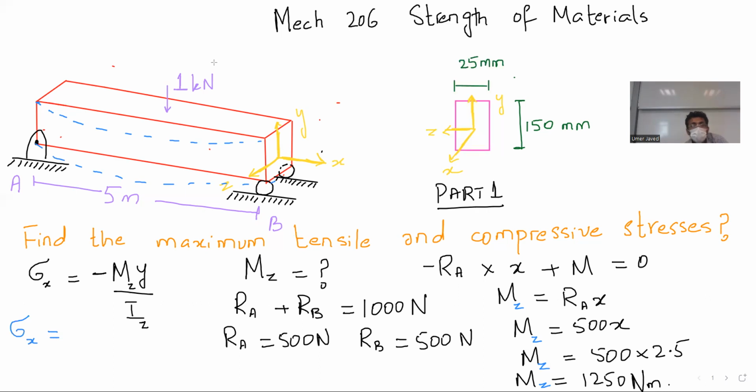I think I need to explain this because we studied this last week. Some of you have forgotten. So this fiber is the neutral axis. Why? Because this is a rectangular structure. And I know that the neutral axis goes through the centroid. So all these fibers right at the center constitute my neutral axis.